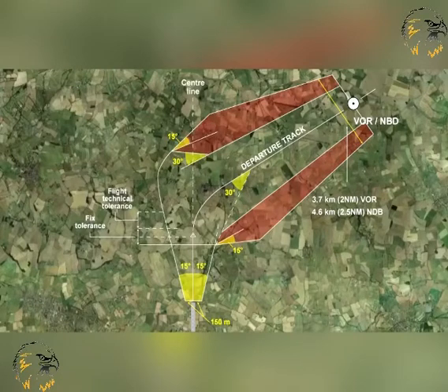You should note, especially for examination purposes, that 30 meters is approximately 100 feet. This fact will allow you to make sense of many of these difficult heights. For example, before metrication, straight flight was assumed to 400 feet above DER, and a minimum of 300 feet of obstruction clearance was guaranteed in the turning area.